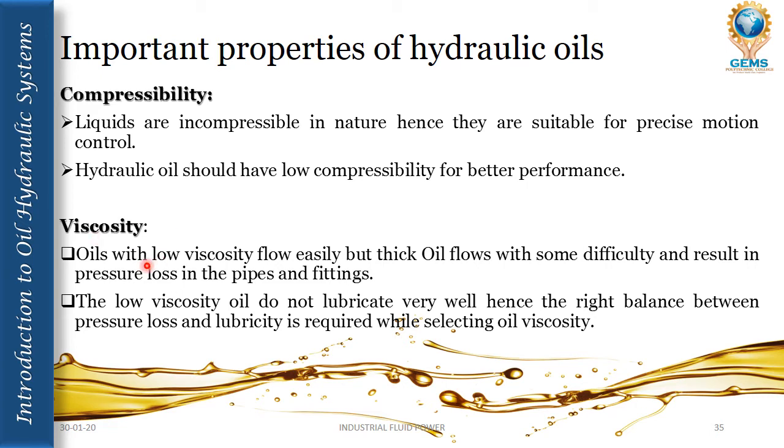And viscosity. Oils with low viscosity flow easily, but thick oils flow with some difficulty and result in pressure loss in the pipes and fittings. Low viscosity oils do not lubricate very well, hence the right balance between pressure loss and lubricity is required while selecting oil viscosity.